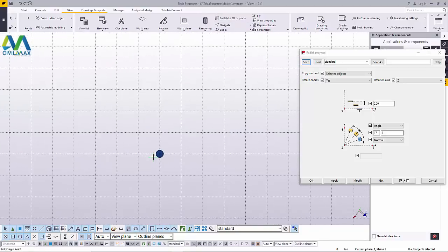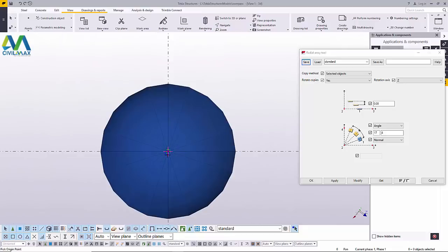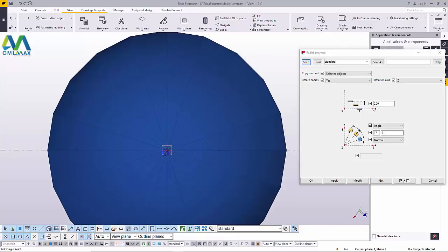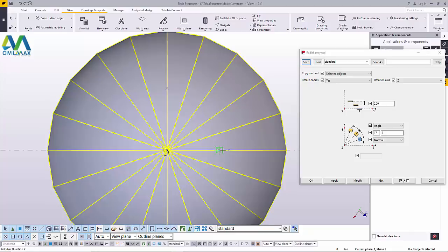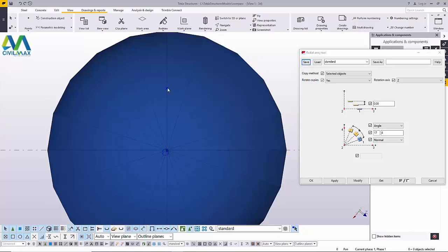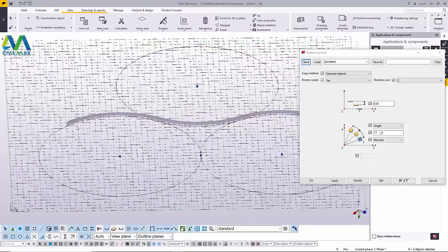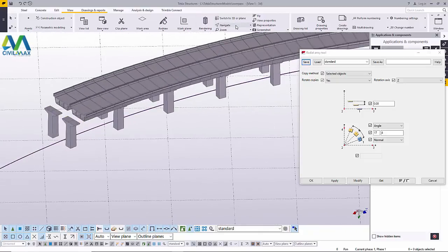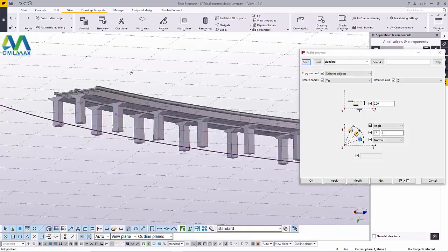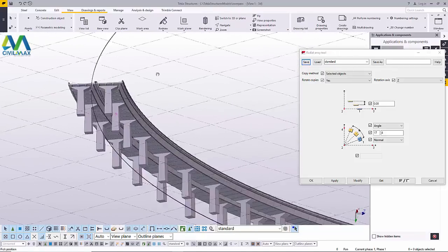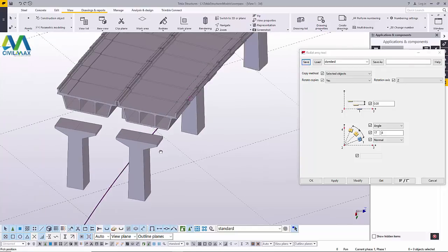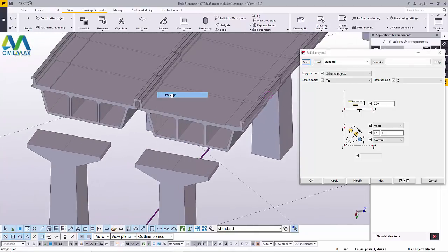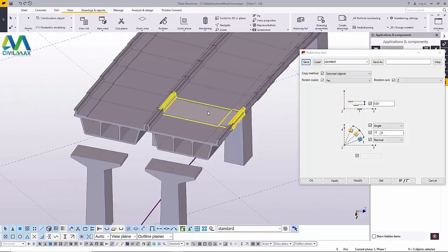We want to use this midpoint or this point of origin as our midpoint. We've clicked on it, and our x-axis will be that, and our y-axis will be that, and press our middle button on the mouse and switch back to isometric view to check whether everything is distributed perfectly well. And this is how it looks, and everything is perfect. You can see one pillar is just slightly off the point, and we'll pull them back to appropriate position.